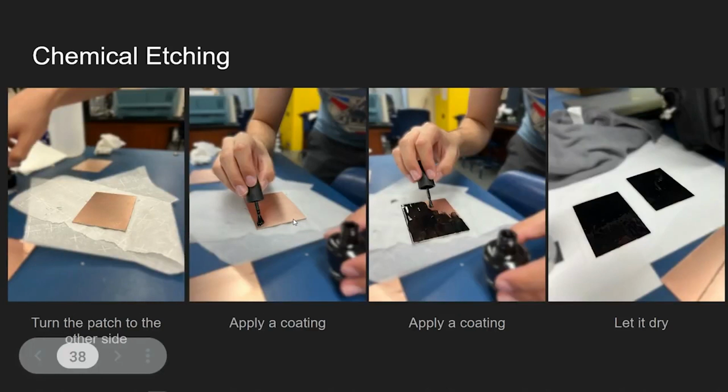Next is the back of the substrate. We can either use the same method to transfer the black coat, or we can just use nail polish. It should be just a single coat, but at the same time, no copper spots should show through it. The nail polish that is necessary for this application is a nail enamel, which means it is just acrylic. It is important because some nail polish needs to be UV cured to set. Usually cheap nail polish is the one that we need.